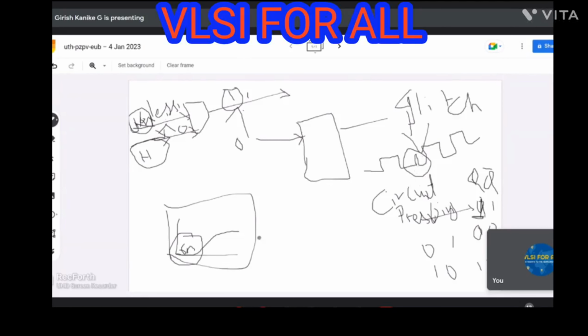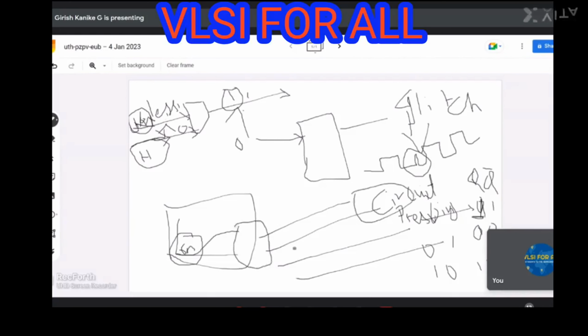And if this happens, for example, if there are two signal routings, with one block connected here and one block connected here, and a glitch happens, there will be crosstalk between these two. Means there will be a coupling capacitance here, so this will affect this. This affects the parasitic extraction, the parasitic I showed you, right? Those parasitic extraction values will change. If those change, your STA will be affected.